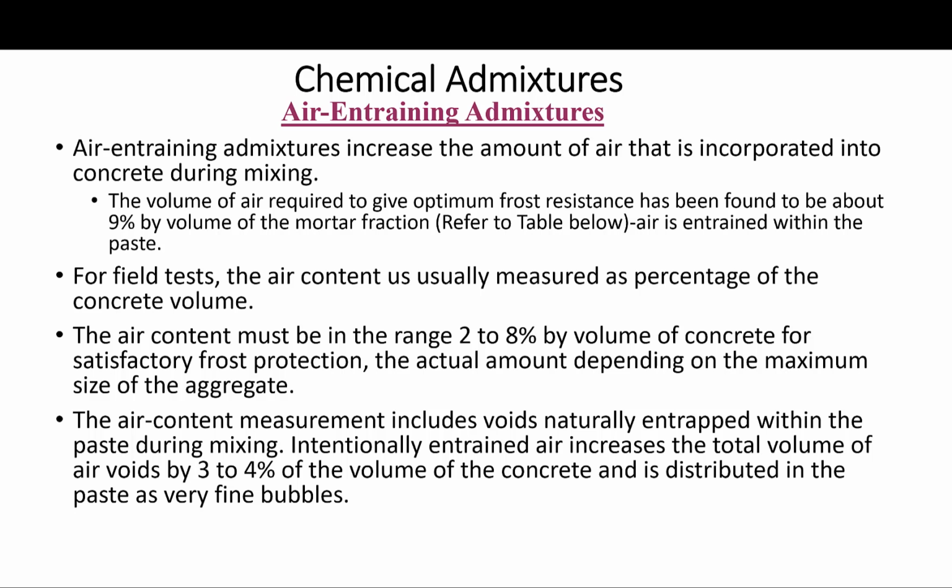This is because more paste is required to provide workable concrete with a lower maximum size of coarse aggregate. So the size of the coarse aggregate impacts the air content because of the workability issue.